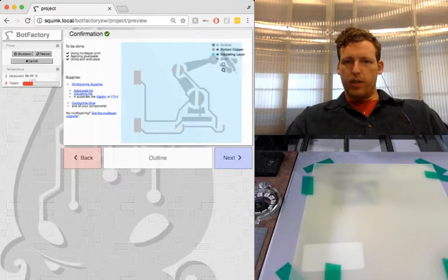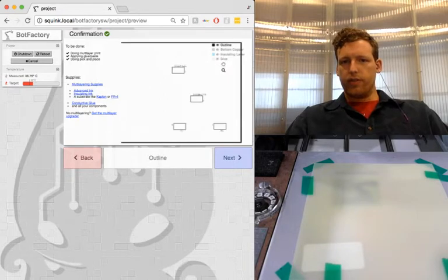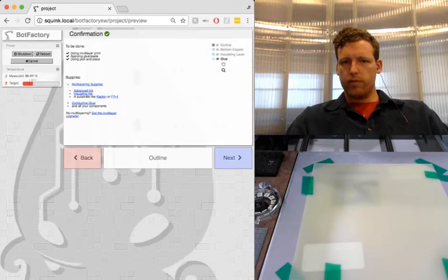The bottom layer is essentially your trace file, so it's going to print this. Your outline essentially defines where the components are going to be, or not the components, but just essentially the edge cuts. It's a .gto, so I think it shows the outlines of where the components go. And the paste file is right here. You can almost see it right here.